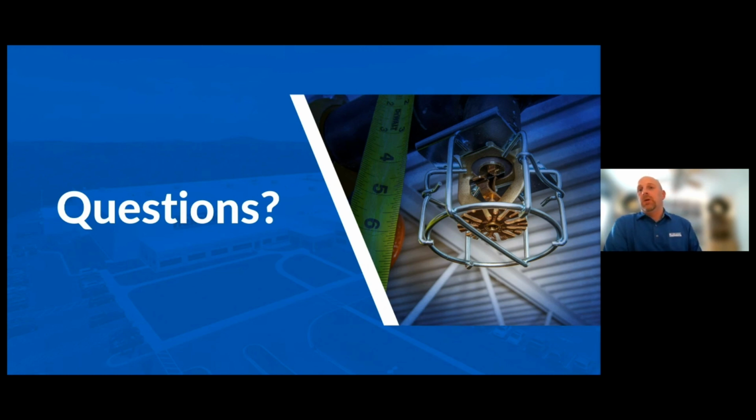Regarding the window sprinklers, is there a minimum distance requirement between the window sprinkler and regular pendent sprinklers? And then the second portion of the question, is the window sprinkler considered quick response? Yes, the window sprinkler uses fast response elements and they're considered quick response. They can be used in the same compartment with quick response sprinklers, and that same thermal sensitivity exists.